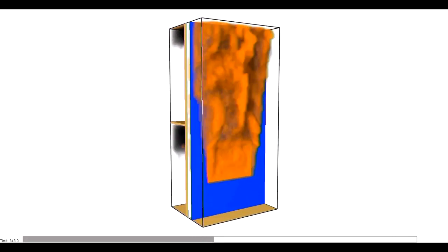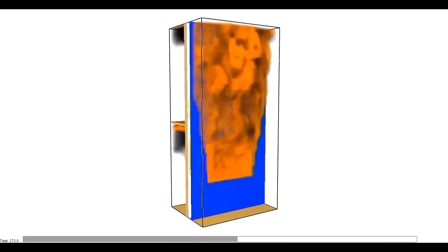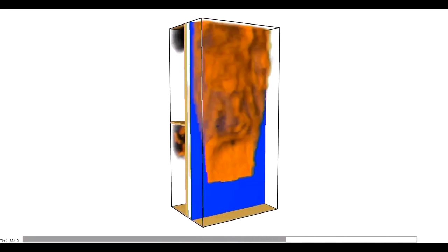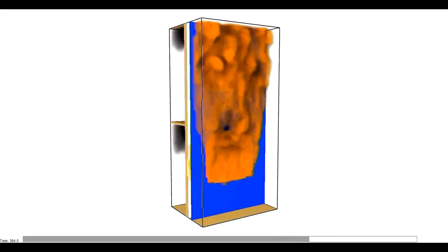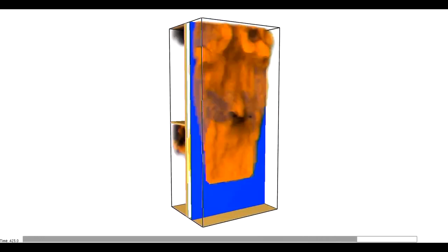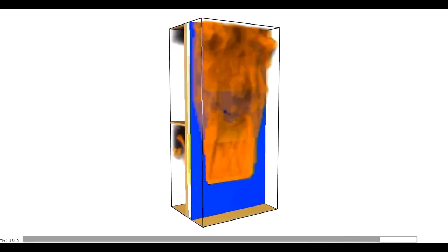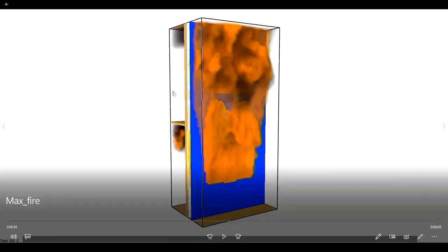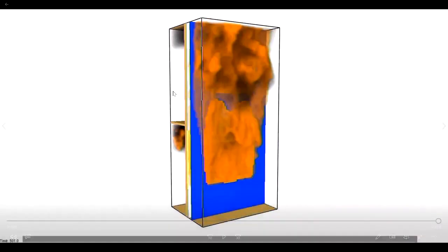So it's a combination of the cladding, which also provides fuel to burn, and the chimney effect, that means the air gap itself, starting from the room of fire origin, spreading to the neighboring rooms up the floors. This is what we can try to understand from a fire engineering perspective.